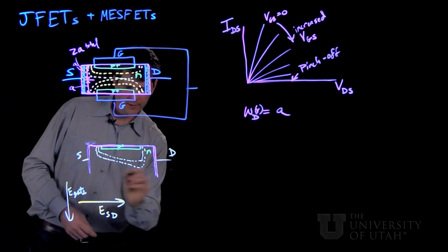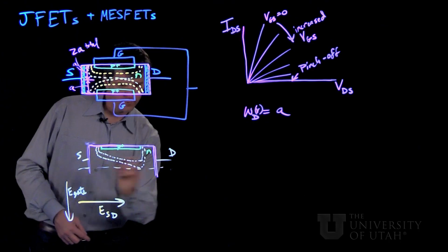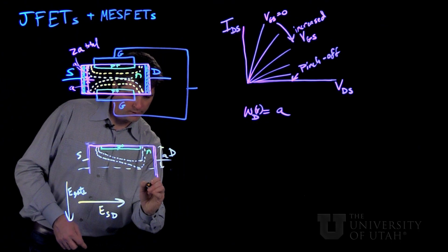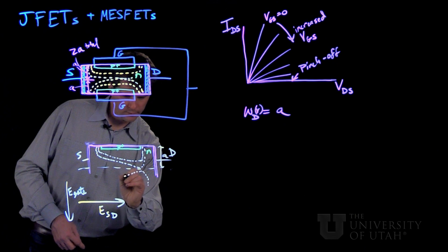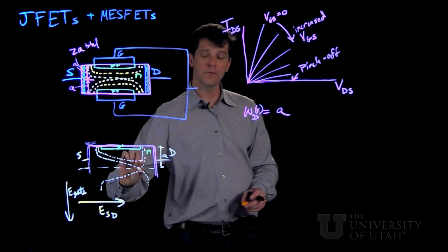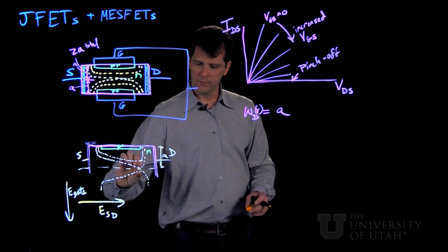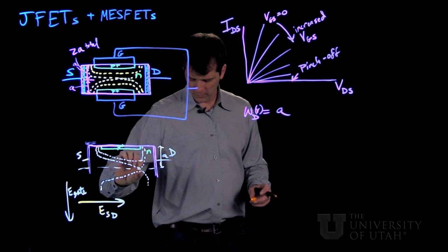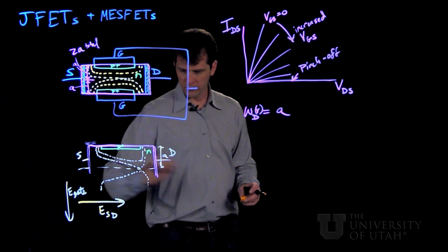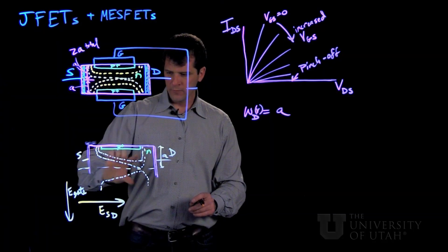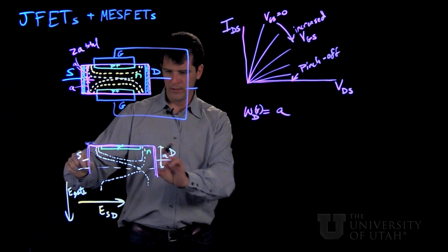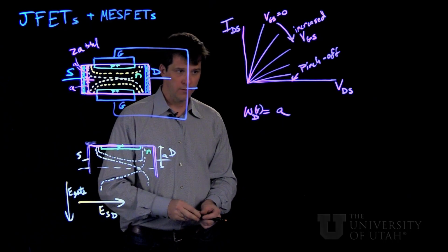And so this is the center line here, this was the thickness A. If we imagine bringing in the depletion width from the other side too, what we see is that pinch-off sort of happens at a point first, and typically it would be on the drain side with the setup we've had here. And to fully pinch off the channel actually takes more and more gate bias as a function of source-drain voltage.